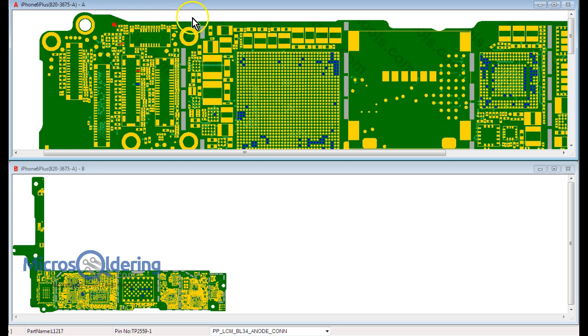Okay. So now that we've isolated which backlight circuit it is, now we can go back and trace it. Okay. So this is the filter that leads into the connector. So we can just trace it backwards. All right. So the filter, we know that it connects to this capacitor right here and this diode, and this is the IC that had the problem. Alright, so here's what we're going to do now. Alright, so this is the bad screen right here.